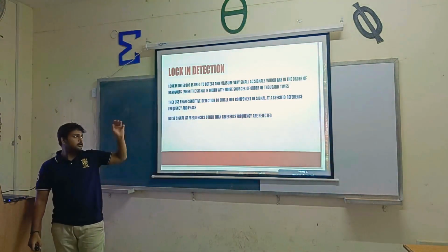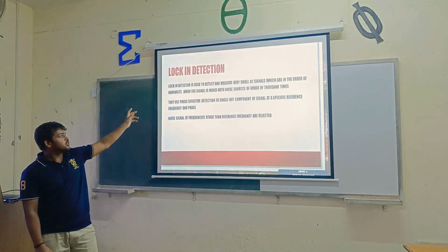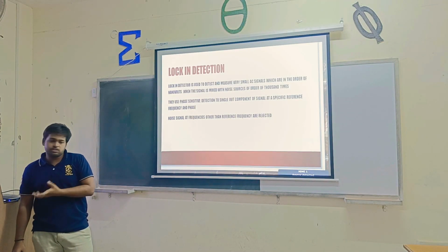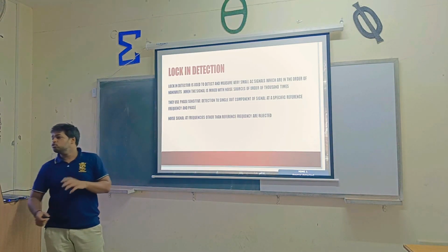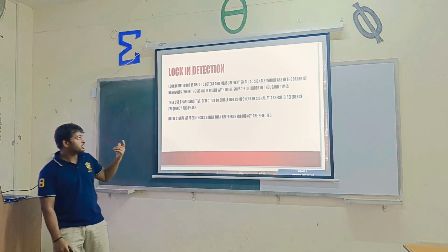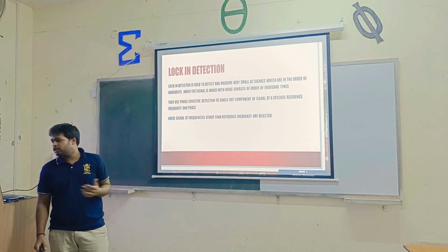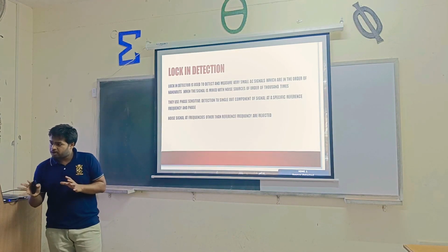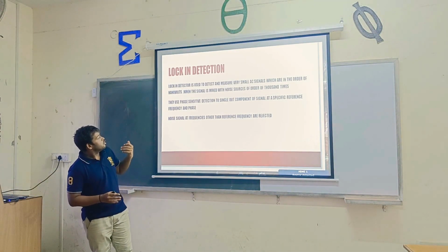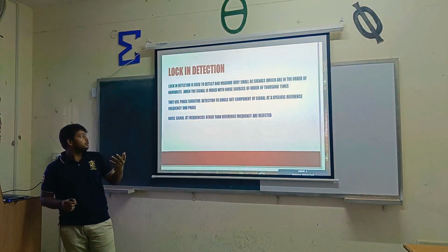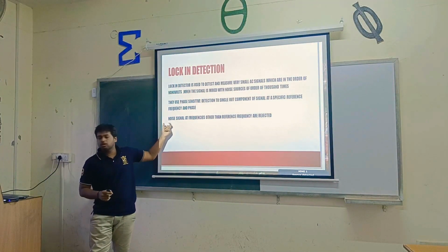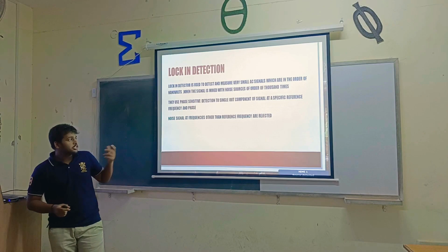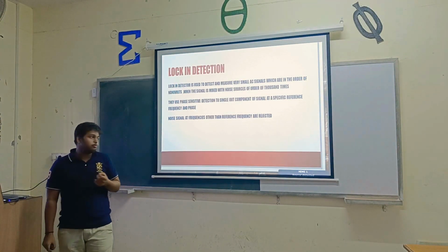Lock-in detection, as I said, we use it to measure very small AC signals, in the order of nanovolts, from the noise pattern that is of higher order. And how is the process used? They use the phase detection technique, the phase sensitive detection technique, to single out the signal component that is mixed in the heavily noisy environment. The other noise components are treated as noise signal. They are discarded, and only the signal component is extracted from the noise in the environment.